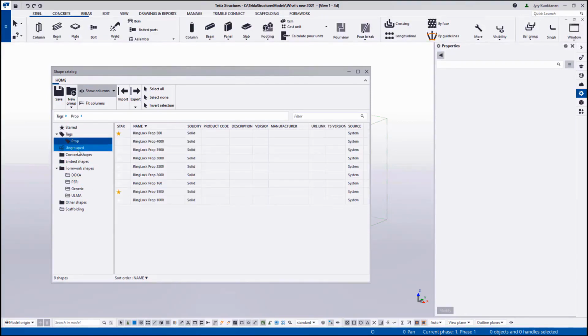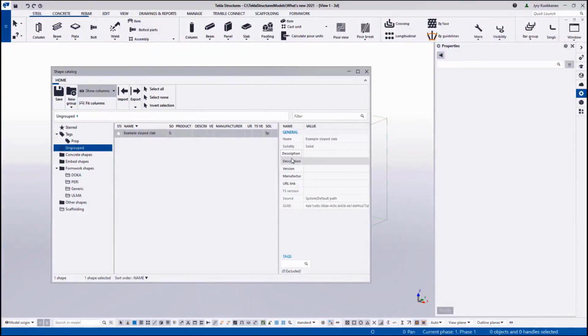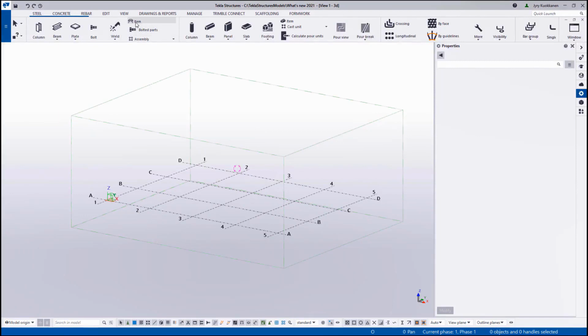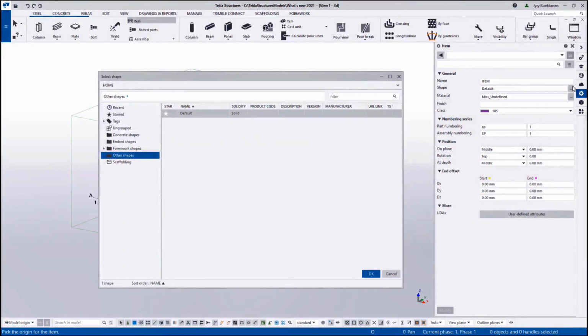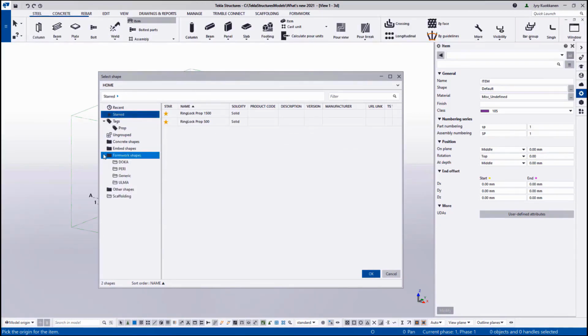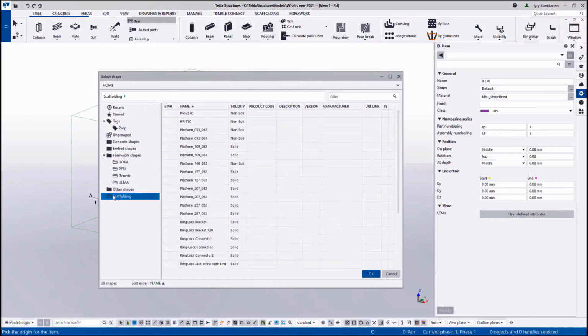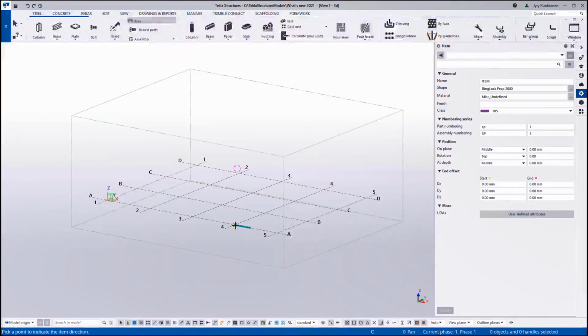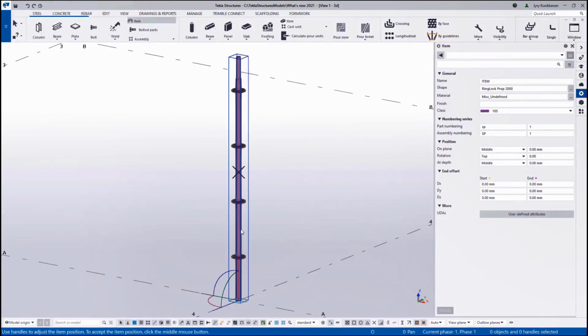What you can also see here in the shape catalog is different attributes that you can here modify as well. Once you save away your settings and start modeling, the shape catalog through the item is slightly different without the option to create those folders, but now the folder structure that you have created is visible inside the shape catalog, and all the tags and start items are there as well. So really nice improvement, helping you to find the correct shapes and organizing the content, so it will help your modeling.